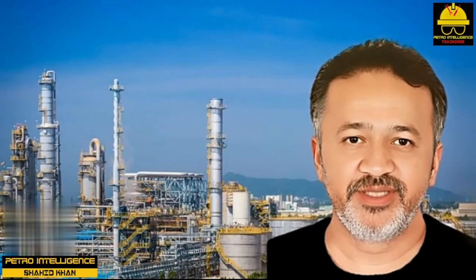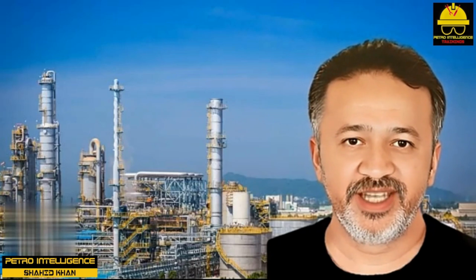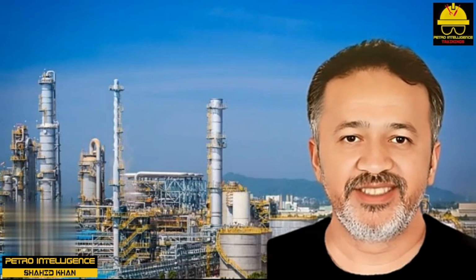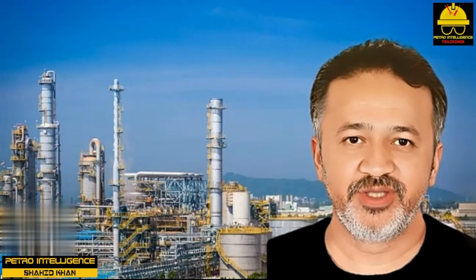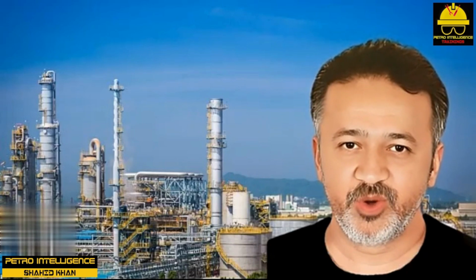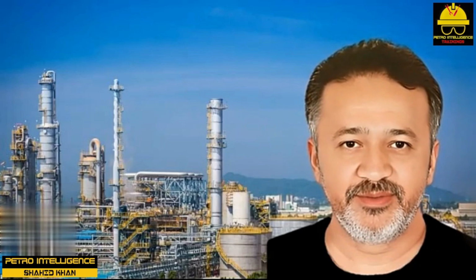However, the largest operating cost for many process units is the energy supply to the reboilers. We should therefore avoid high reflux rates and try to achieve the best efficiency point for distillation tower trays at a minimum vapor flow. This is best done by designing and installing the tray decks and outlet weirs as level as possible. Damaged tray decks should not be reused unless they can be restored to their proper state of levelness, which is difficult if not impossible.